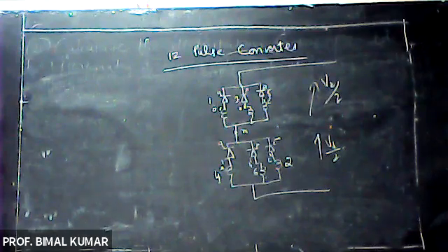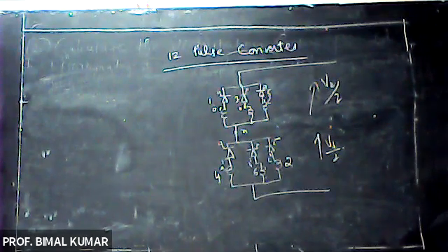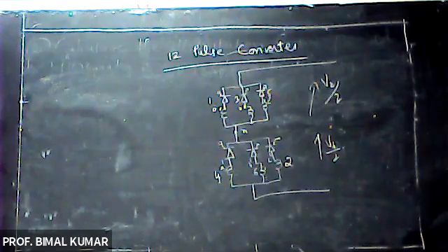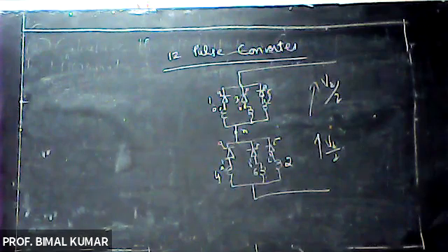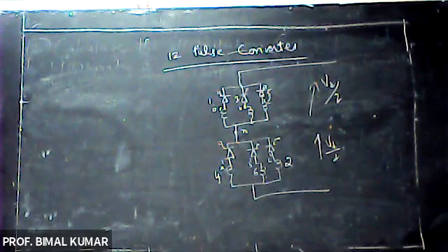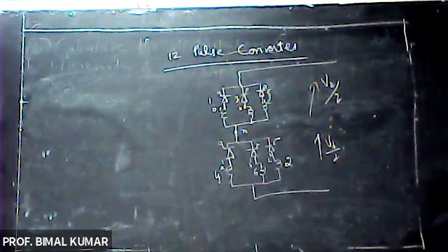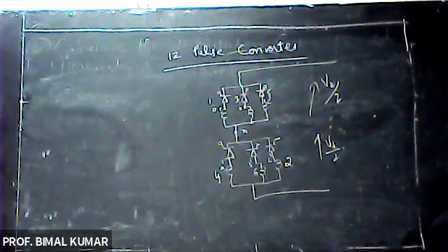Transformer, in the last lecture, we just defined what is transformer utilization. Transformer utilization is the ratio of the average peak inverse voltage to the average DC voltage. That is known as the index of valve utilization or utilization of the transformer, right? This may be improved if we are using this type of connection in case of a 6 pulse converter.